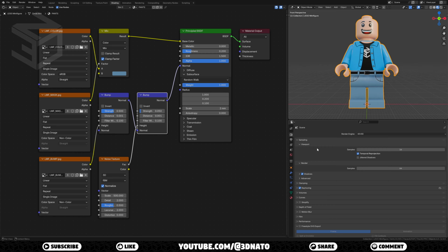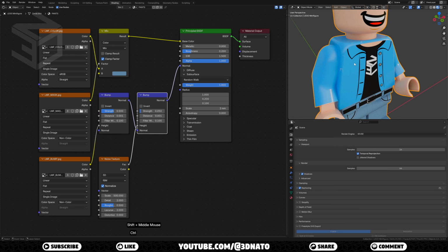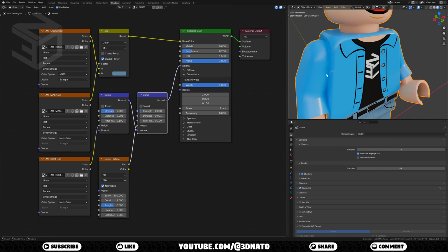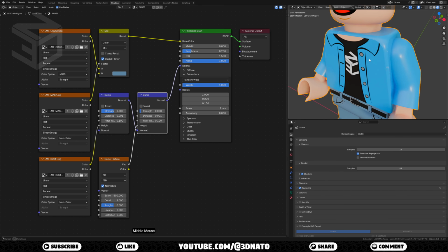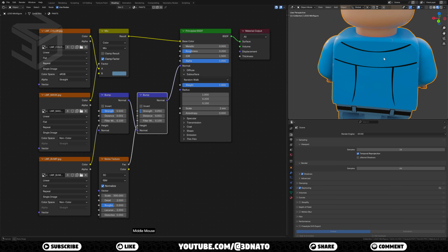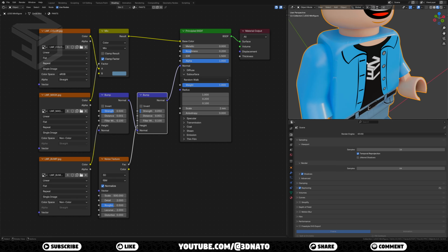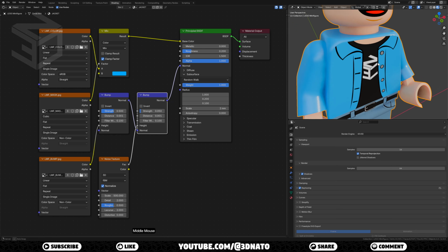This part here took me some time to figure how to fix. Throughout the creation of this course, I wasn't getting this weird shading issue. You can see it here, and here where we did the smooth vertices on the torso. These ugly shadings all around only appeared after the materials. I have tried a lot of things to solve it, and it turns out the fix was quite simple. Just select the jacket material and set the mask map interpolation to cubic. And now we can see the ugly shadings gone.